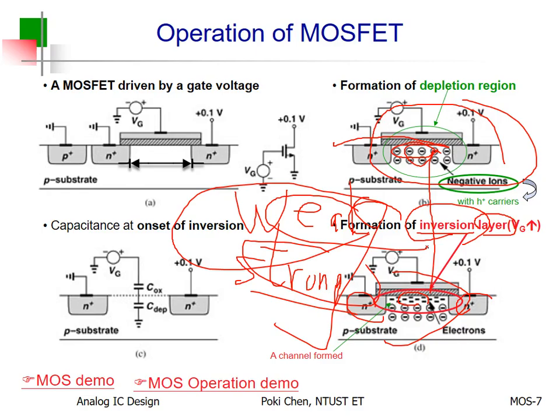But what's the difference between strong inversion and weak inversion? In brief, strong inversion is what you learn from microelectronics for saturation. Later I will show you the equation: ID equals 1/2 mu COX W over L, and so on. That is for strong inversion. And how about weak inversion? Oh, fantastic!